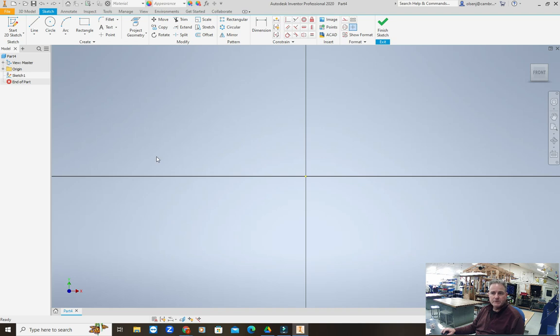Alright, let's go ahead and draw the roof using the line tool, and I'm going to do it from a different angle as well. So I select line. Up here in this quadrant, I'm going to start a line that goes straight down, making sure that I'm at 90 degrees, and you can see on the right there, the dialog box shows that I'm at 90 degrees. And I'm going to create a line segment that is 0.75, enter. You can see my dimension over there is 0.75, and I have a 0.75 line segment.